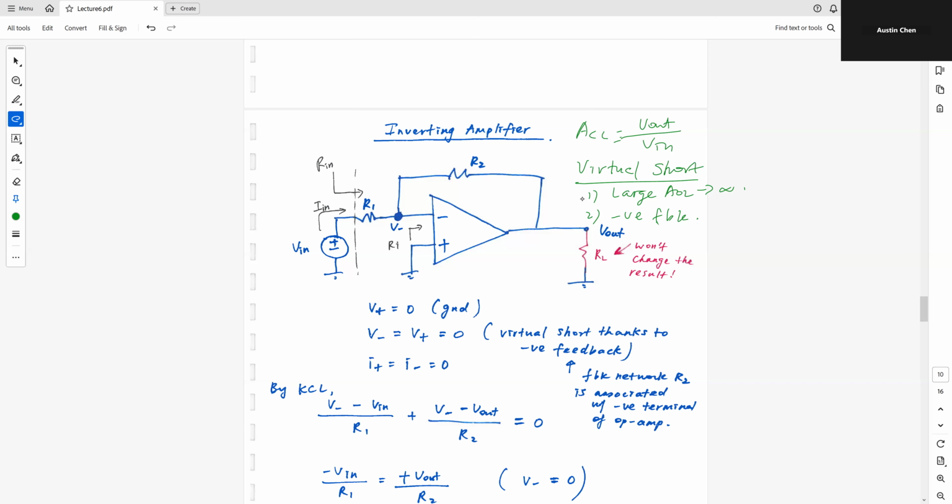One thing that you check, as I mentioned earlier, is the signal going back from the output to the input. It has to go into the negative terminal. In other words, this is my output, and I have this feedback network, part of it is my R2. Through this feedback network, the signal has to eventually go back to the negative terminal of your op amp.